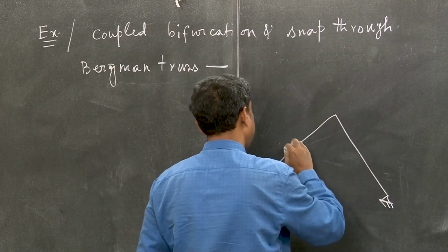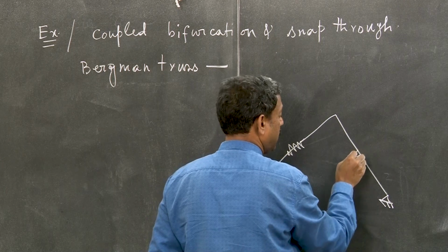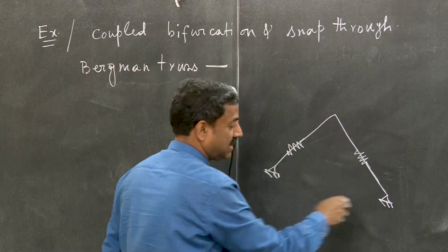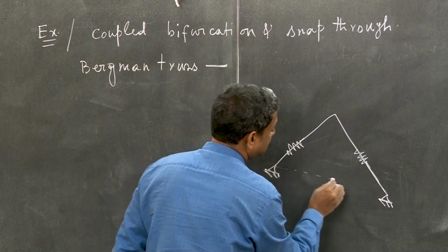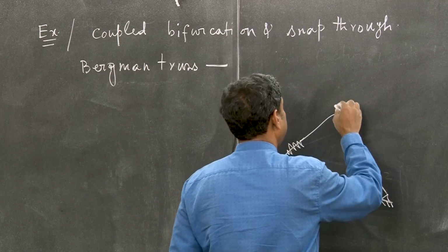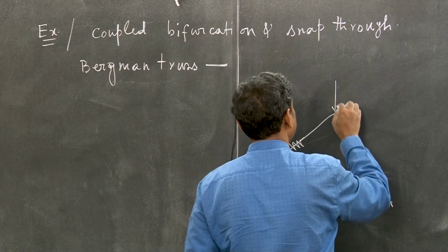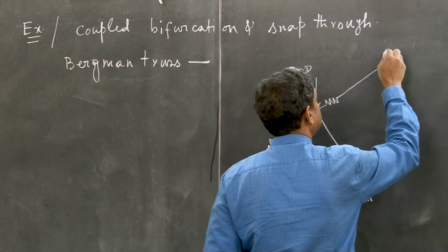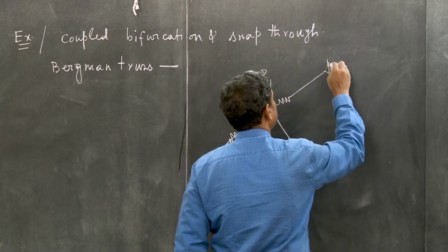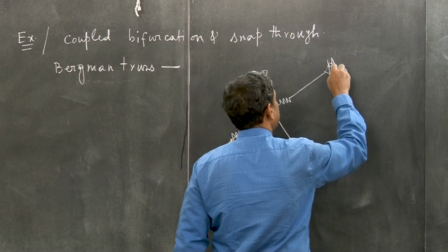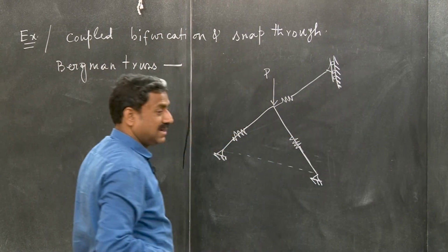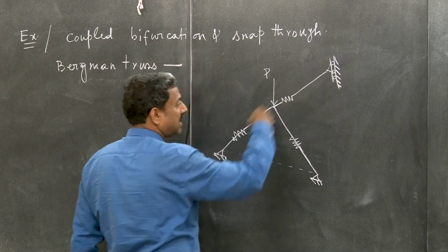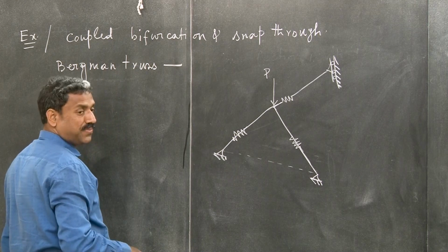So there is a spring, because of spring stiffness or axial stiffness. But so this is nothing but what? This is called the von Mises Truss, right? So this axial load P is there. In addition to that, there is another spring that is attached here and supported here. So it's a combination of a von Mises Truss restrained by another, additional spring.